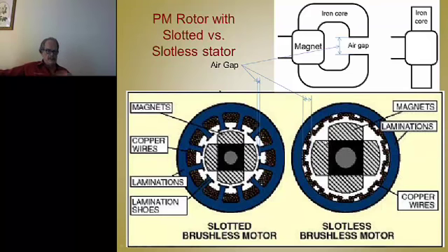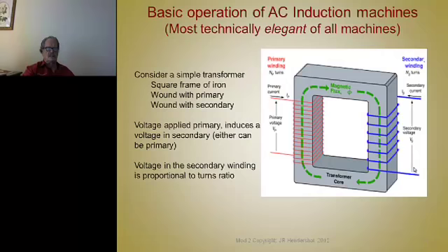So that's why you've got to commutate. As soon as it moves over here, I've got to change the polarity of the current in the new coil that's under that pole to keep it going. So this one's attracting and that one's repelling. When this moves around and covers these two coils, I've got to have this one repelling and that one attracting to keep it going in the same direction. So even though there are forces on there, according to the previous slide, there's still this attracting and repelling force. And to me, that's easier to get my arms around, to think of it like that.